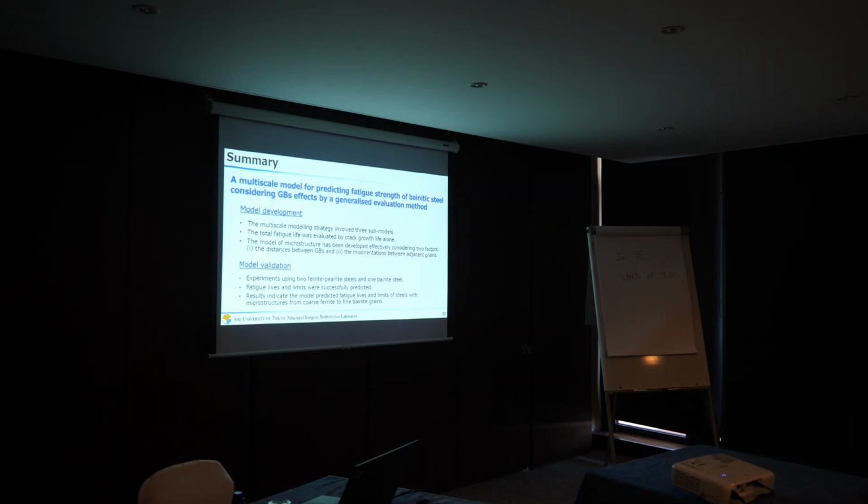The very important point is that the total fatigue life was evaluated by the crack growth life alone, and our model of the microstructure has been developed effectively, considering the distance between grain boundaries and the misorientation between the adjacent grains. And we validated our model by experiments using two ferrite-pearlite steels and one bainite steel.